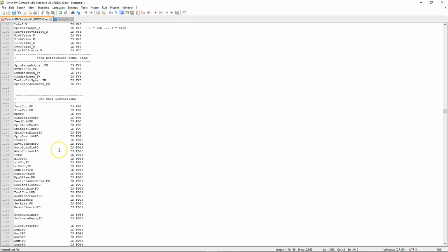Okay. These one-shots are essentially the things that could be needed when, let's say, you've got a momentary switch. In your logic, you can have something where when you click on a button, you want the thing to latch. Even though the button itself isn't latched, it's only a momentary turn on, turn off the moment you release it, but you want that particular setting in the PLC program to be latched because you tapped it once. This is where you would use a one-shot.